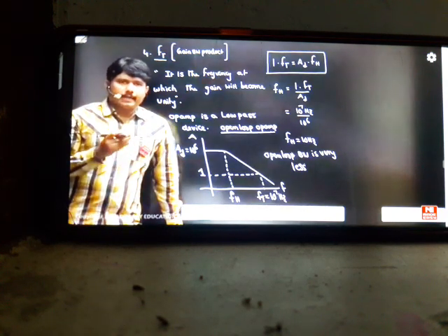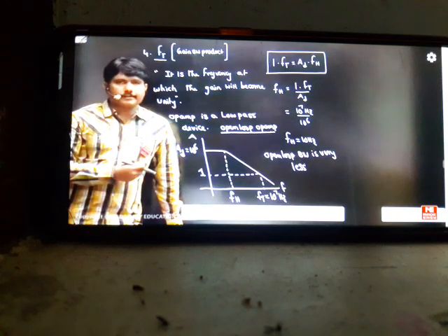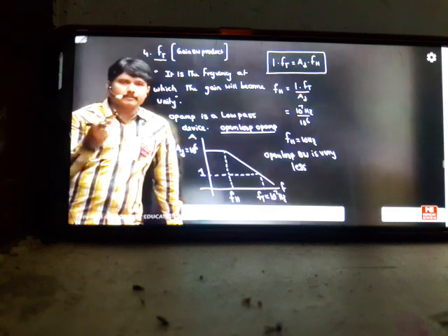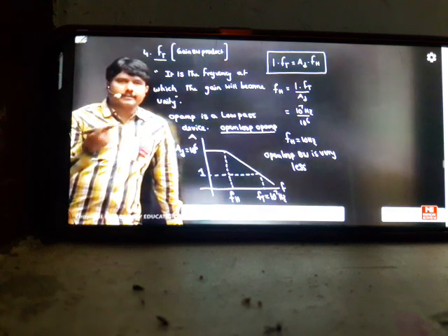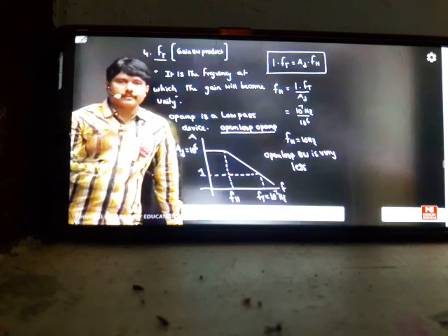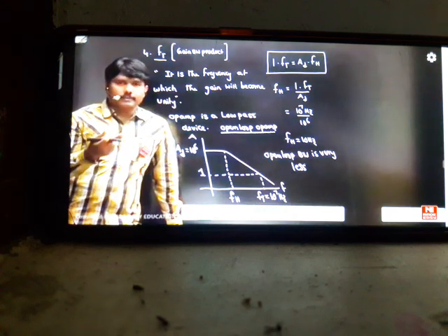Now sir, you are telling that an amplifier has high speed. Amplifiers will work in megahertz. How is it possible if the bandwidth is very less? I can say that rise time, what we studied in multi-stages, is inversely proportional to bandwidth. As the bandwidth decreases, the rise time will increase. As the rise time increases more and more, the system speed will fall. But how are you telling that in an amplifier the system speed is very high? In the open loop system, the system speed is less. But in the closed loop system the speed is more, you are telling.